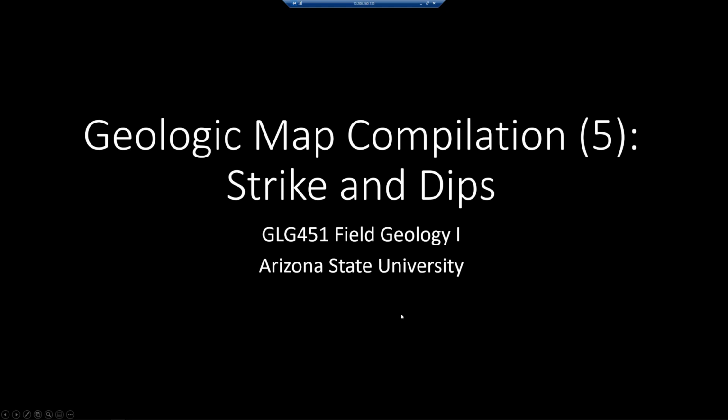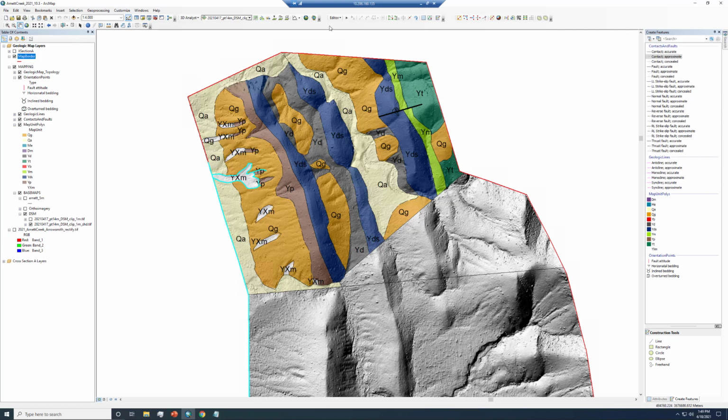Okay, now let's do the point features on our map, which are the strike and dips. Alright, we got a nice looking map. The first thing you can see is over here on our orientation points, we have some strange labeling. That's because the point features in ArcMap are actually fonts, so we need to add some symbols.